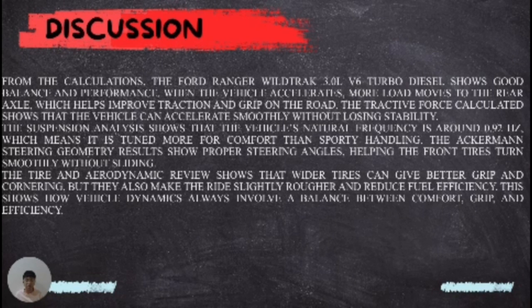The Ackermann steering geometry ensures the front tires turn smoothly without sliding. The tire and aerodynamic review confirm that wider tires give better grip and cornering ability, but they also make the ride rougher and reduce fuel efficiency. This shows the vehicle dynamics always balance comfort, grip, and efficiency.